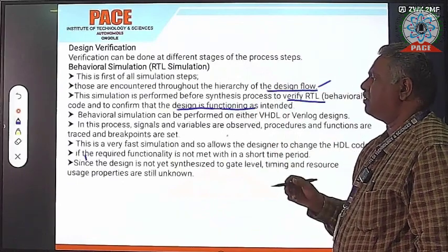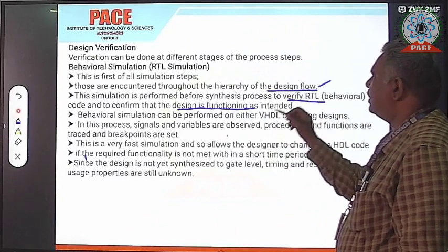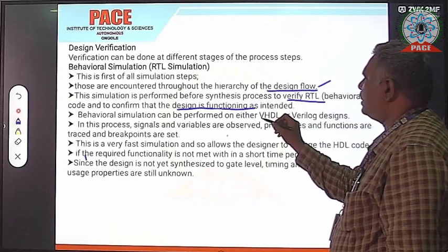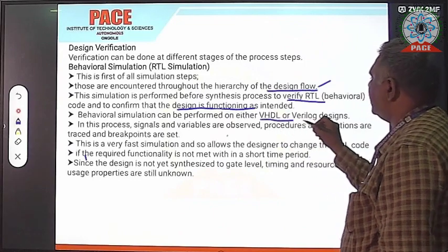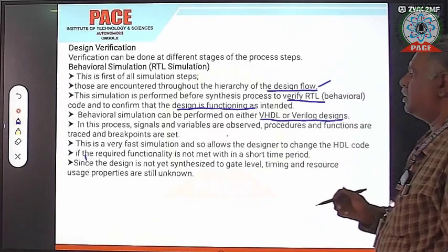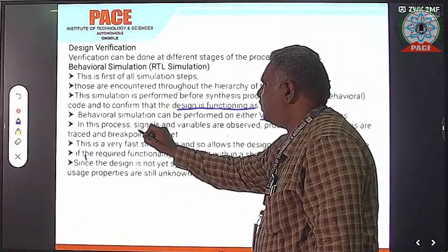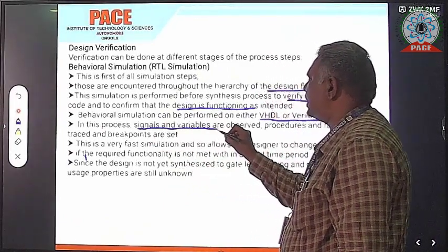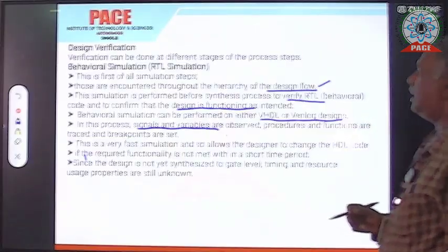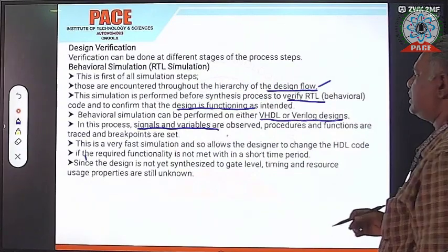We are going to write the behavioral simulation or RTL simulation by using VHDL or Verilog designs. One more important point is we are going to verify the signals as well as the variables in these functions. It also allows the designer to change the VHDL code.